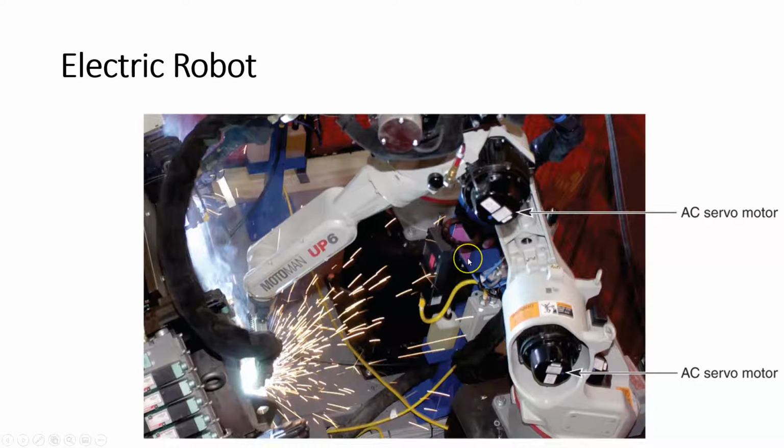An electric robot, like the robot that we're using, most of the robots in an industrial environment are either going to be electric or hydraulic. We have pneumatic robots are used. They're typically smaller robots, right? Because pneumatic pressure used to move things is not going to be as pressure insensitive as electric or hydraulic, meaning that a pneumatic robot is not going to be as stiff. Okay, that's one way that we can explain it.